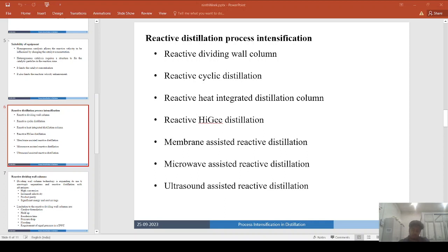And then, to perform the separation task, why limit yourself to distillation, because distillation operates upon fluid solutions. If you have particulate matter, then you can combine membrane separation with the reactive distillation setup. So here three different unit operations or tasks are combined.